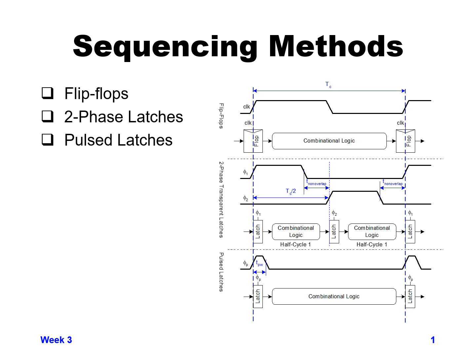As long as it does, then the next time the clock goes from low to high for the next clock period, it will capture the value that the combinational logic is sitting there stable, waiting for the flop to capture. And when it captures a new value, it will send that value down to its receiving logic, but the flop on the left-hand side will also capture a new value and start a new value of combinational logic evaluating, and that just continues cycle after cycle.